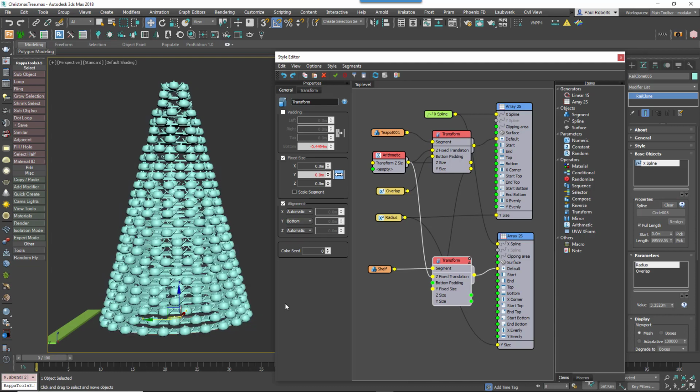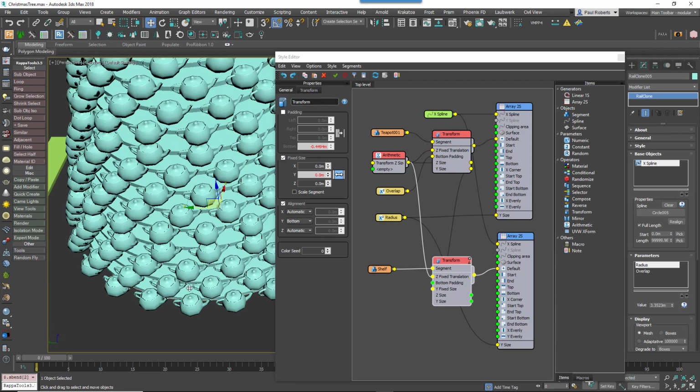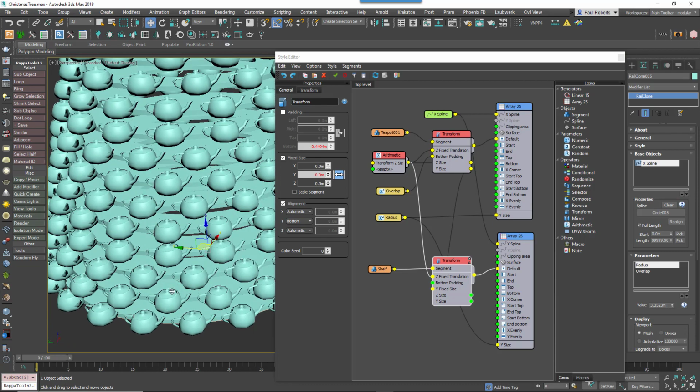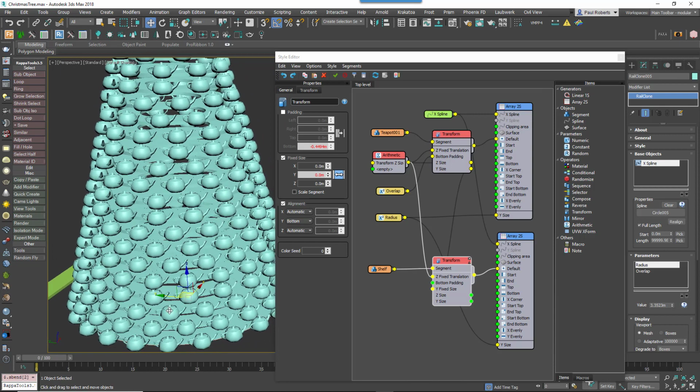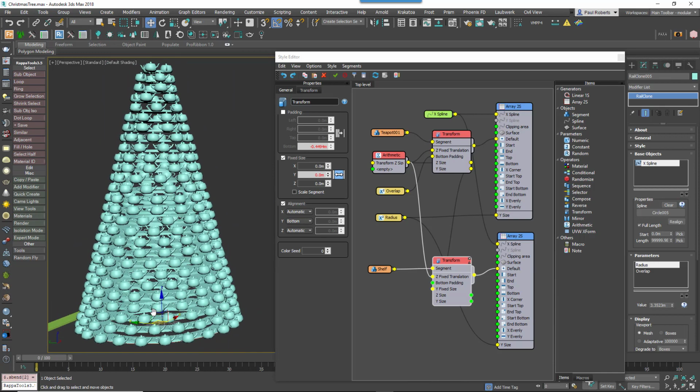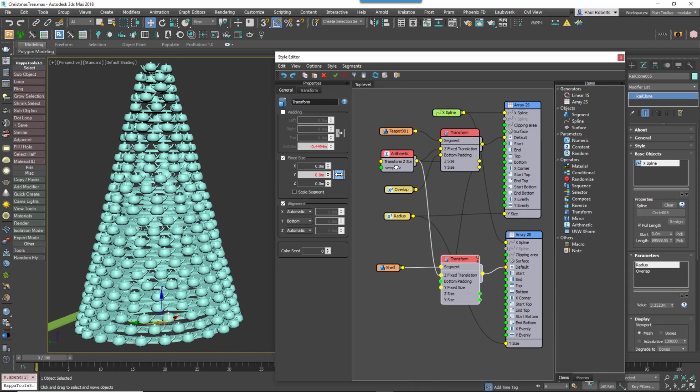Next, we'll align the outside of the shelf to the outside of the teapots. To do this, first change the Y alignment for the shelf to bottom. Now the outer edge of the shelf is aligned to the spline, and all we need to do is move it back along the y-axis, the depth of the teapot. This might seem like an odd way of doing things, but it allows us to have a shelf that is deeper than the teapots and everything's still aligned automatically.